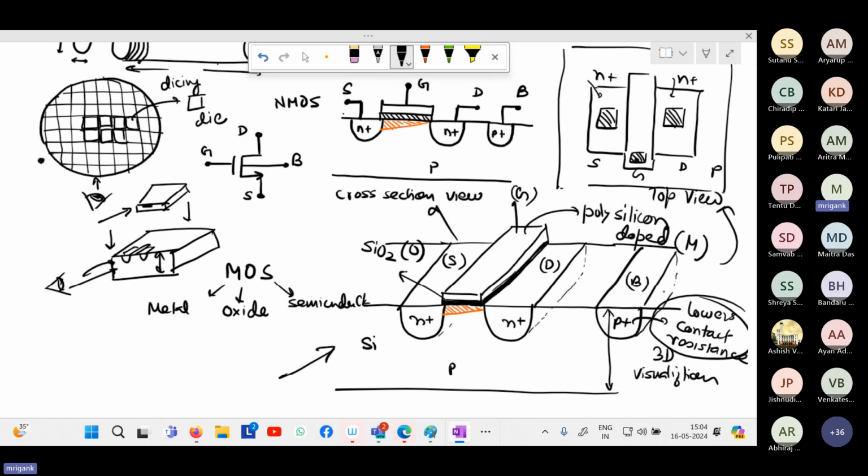But for the time being, you should remember that directly contacting the silicon with metal will create a Schottky junction. It will create higher contact resistance. We therefore apply a highly doped region. We select a pocket where we heavily dope that silicon and then connect with the metal. So for P-type substrate, we have a P plus junction, and then we apply the metal, right? We are not applying an N plus junction because again, it will form a diode, right? The substrate is P. So P to P plus, and then go to metal. That will have reduced contact resistance.